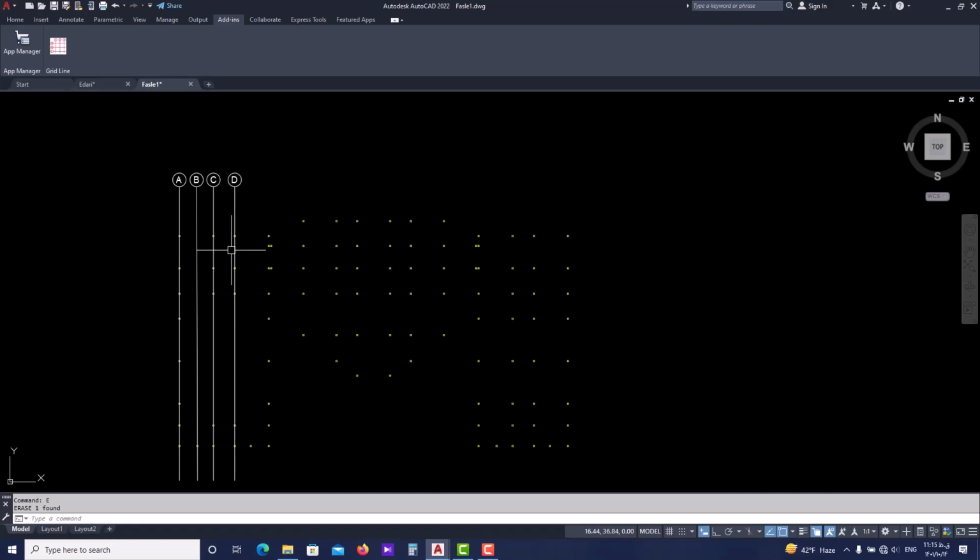Let's just activate the grid line again and redo the settings, but there is a point here. This is very important. You have to put the label on E because you have already put the labels up to D. And now the rest of the settings. Okay, place start, then extension 5, and frame is 1. Okay, we said we're going to work with the help of the auxiliary lines.